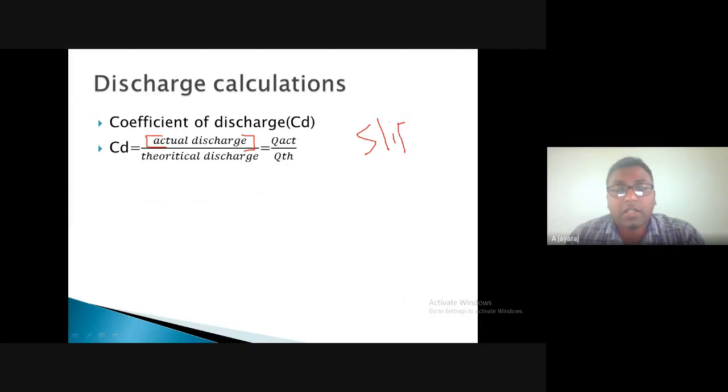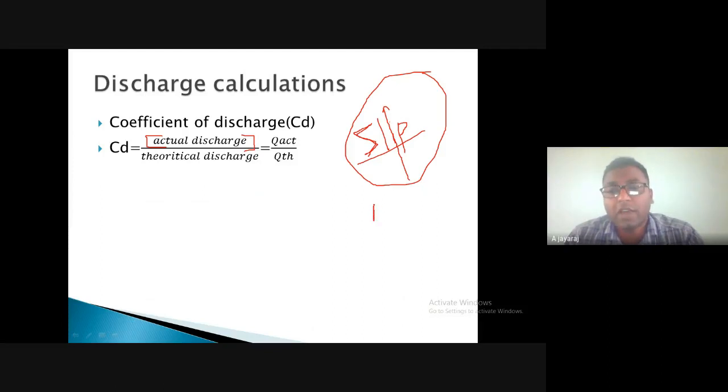There occurs slip in many forms. It may appear in the suction as well as during the delivery stroke. Some of the fluid gets slipped away or may not be carried into the delivery line, and also the cylinder may not be completely filled, so it will have a certain volumetric efficiency with it.